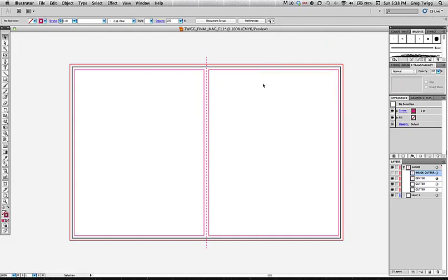And that now places two of these elements as my gutter, which is a little cleaner instead of having that box up there. So the great test is to turn on the box of the inside gutter and just see if things line up. If things line up, then you've done things correctly. If they're not lined up, then you've done things incorrectly.